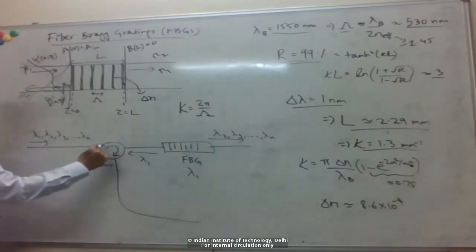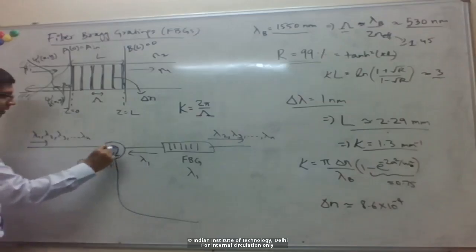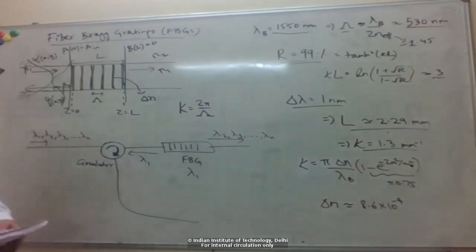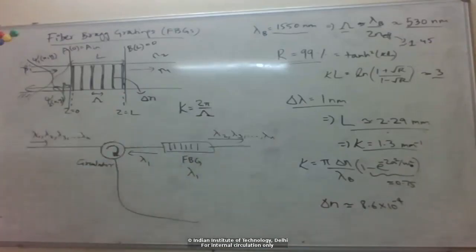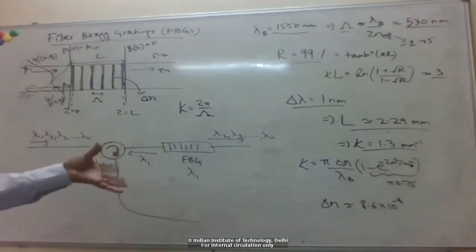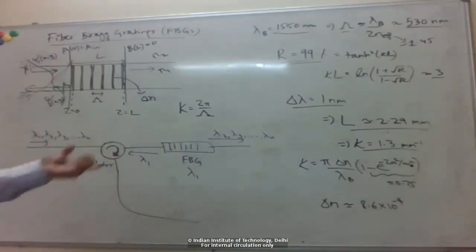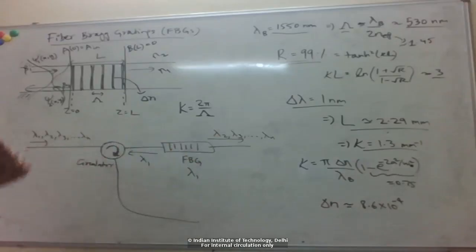Okay, and this circulator device is like a non-reciprocal device. So it works on the concept of optical isolation. So you might have learned about isolators, optical isolators, from your basic optics course, right? They allow light to travel in one direction but not the opposite direction, right? For example, typically that is done using magnetic fields and some magnetic material which rotates the polarization, right?